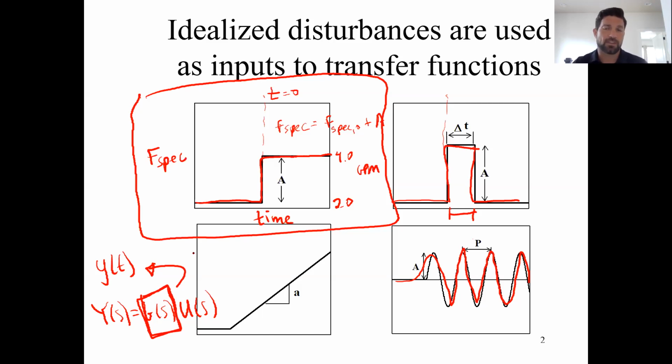Now the point of this chapter is to avoid doing all of the math to derive the transfer function and multiply it by the input. Again, in this case right here, we said the input is a step function, which is going to be A over s. But we don't have to multiply G(s) by this in order to do this. We're just looking at the form of the transfer function. This is saving us from doing all the math to convert it to the time domain and then sketching the function in the time domain.